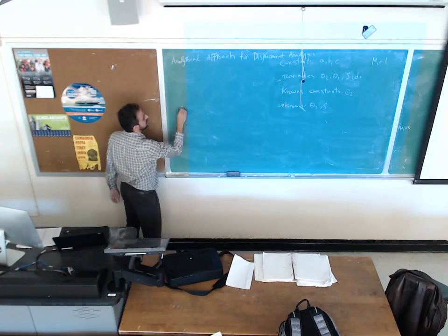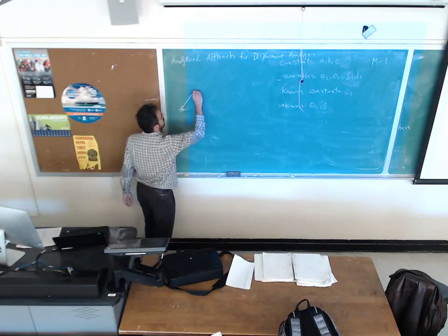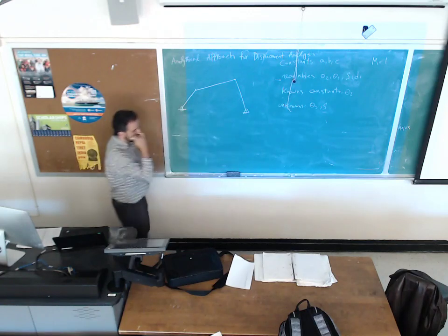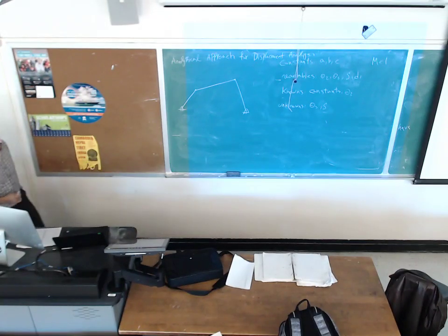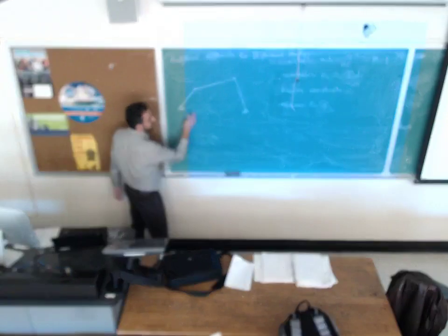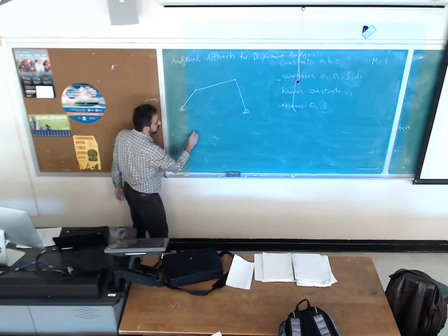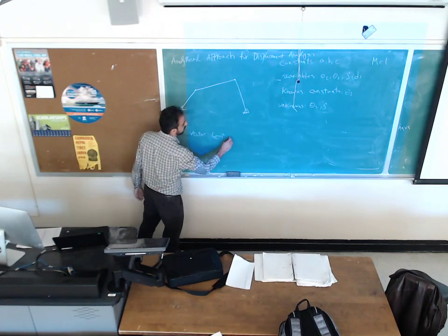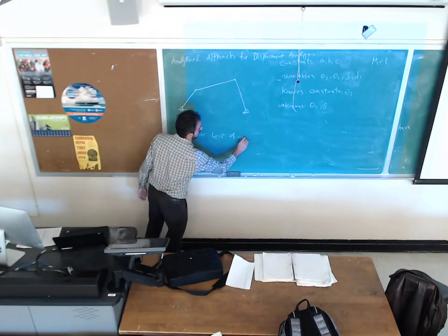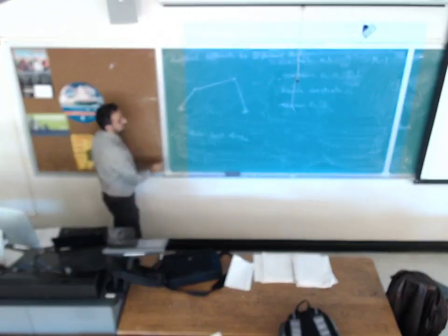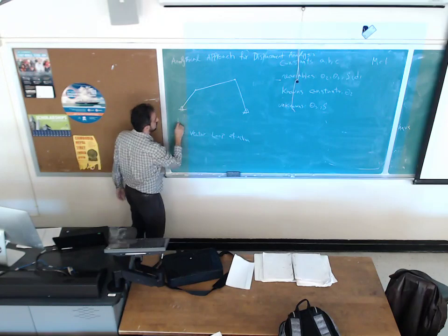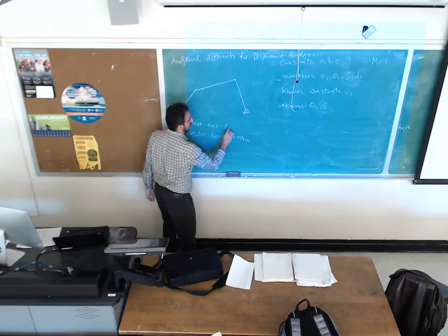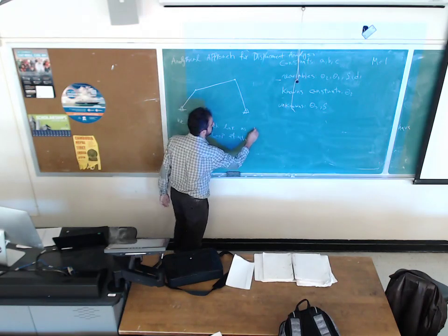So suppose we have a 4-bar mechanism. Like this. If you remember everything on analytical approach, it's starting from vector loop equation. In analytical approach, we treat each link as a vector.